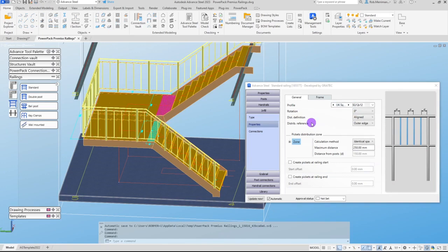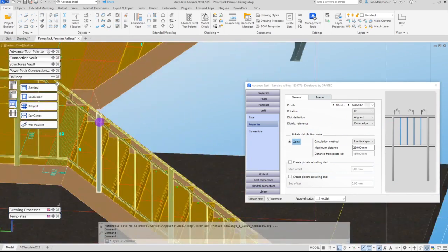Now, one of the issues that you might encounter with the out-of-the-box railing macro is the spacings, where you have to set the spacing from the center of the post to the center of the first infill bar, center of this post to the center of this one, and then the centers, so you can't get your equal centers everywhere.